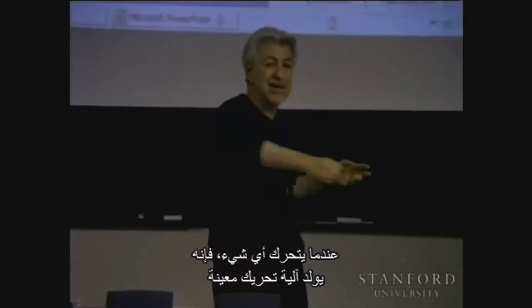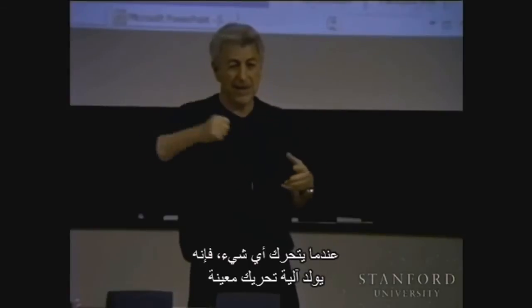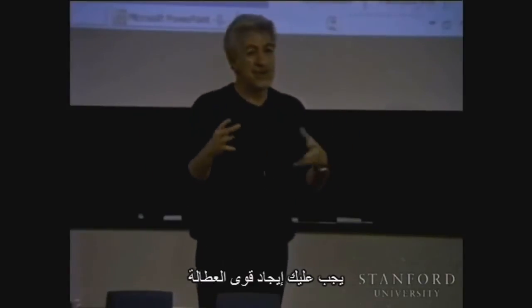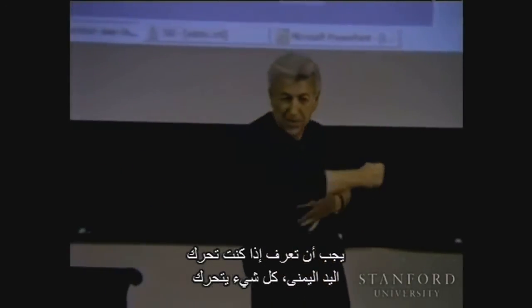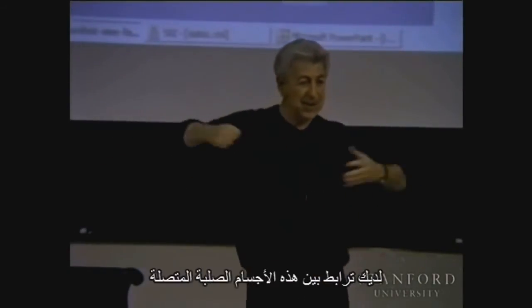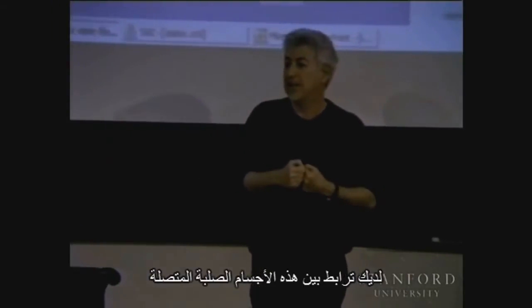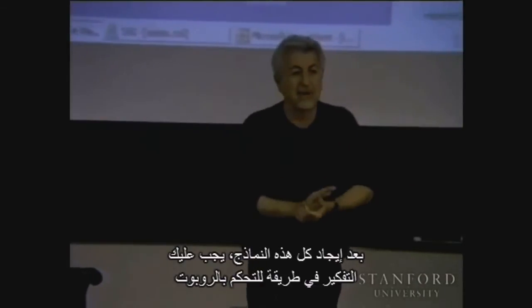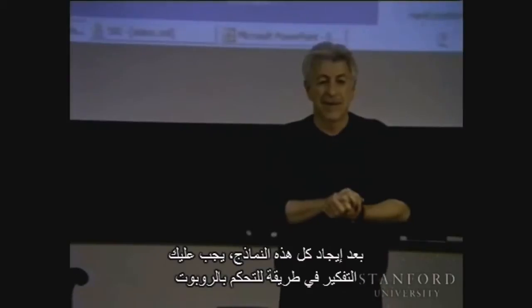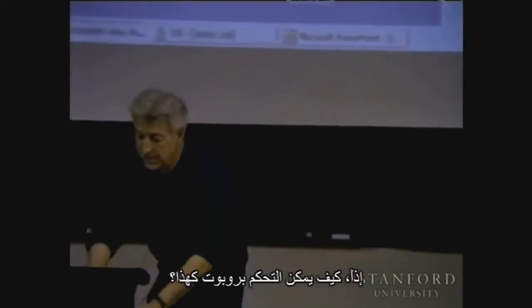And when the thing is moving, it generates dynamics, right? So you need to find the inertial forces. If you move the right hand, suddenly everything is moving, right? You have coupling between these rigid bodies that are connected. So we need to find the dynamics. And once you have all these models, then you need to think about a way to control the robot. So how do we control a robot like this?